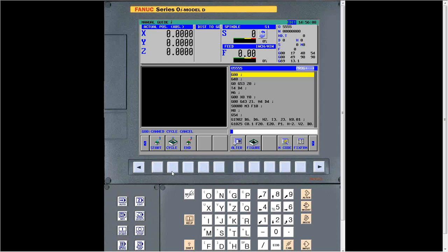That doesn't matter whether you're on the G-code side or the conversational side. So if you orient that at the beginning and measure that distance, then run a G-code program, it would still pick up the thread. What a lot of people want to do is not use the threading cycle within Manual Guide i, but use their G76 threading cycle that they use all the time, and it will work for that.